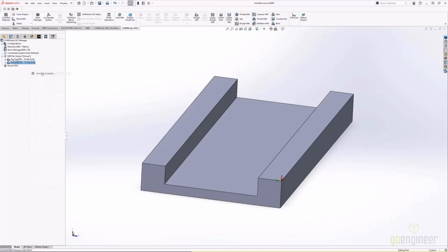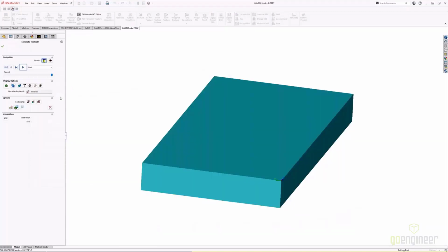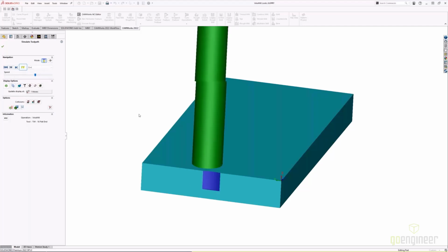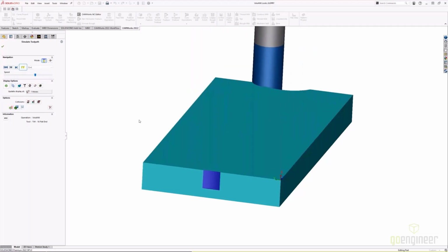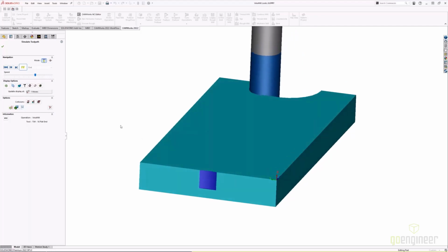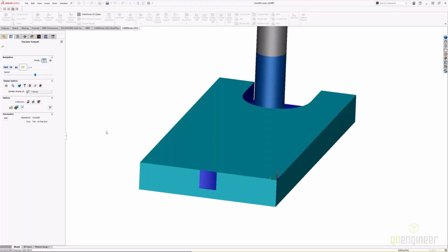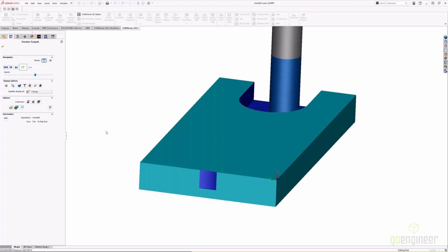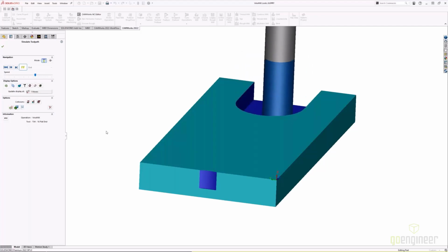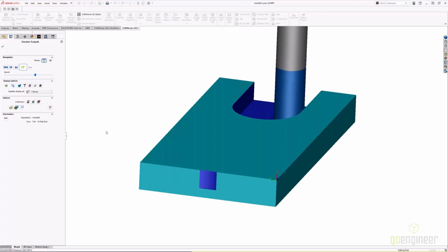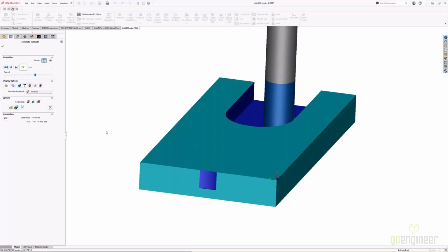And just for this simple demo, I'll just simulate this toolpath. And I'll bring the speed down, and we can see how these entries come in. So we can see that it's maximizing tool engagement. This slot is substantially shorter than the cutting area of my tool, but we can see that it's just coming in and taking an even arc cut every pass. This way, it's not doing a big slotting pass all the way through the first time around.